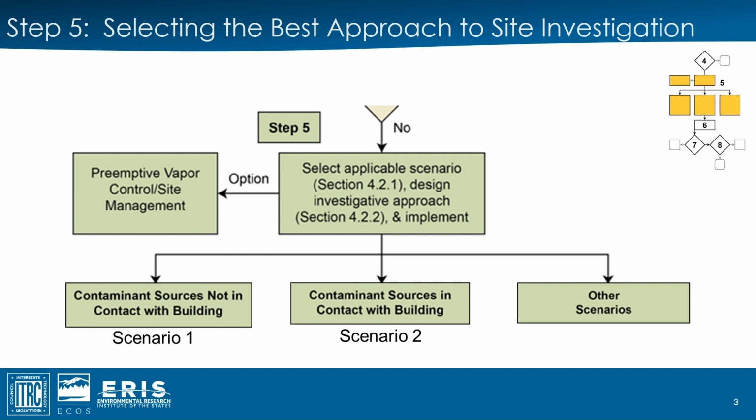It's also important to collect outdoor air samples during indoor air sampling to try and assess whether indoor air concentrations are being affected by background sources in outdoor air. Lastly, it's important to note that collecting a representative subslab vapor sample can be challenging given the tendency to encounter significant spatiotemporal variability in subslab vapor concentrations, and because subslab vapor can be affected by background sources in indoor air. Bounding the variability often requires multiple sampling events at multiple locations.